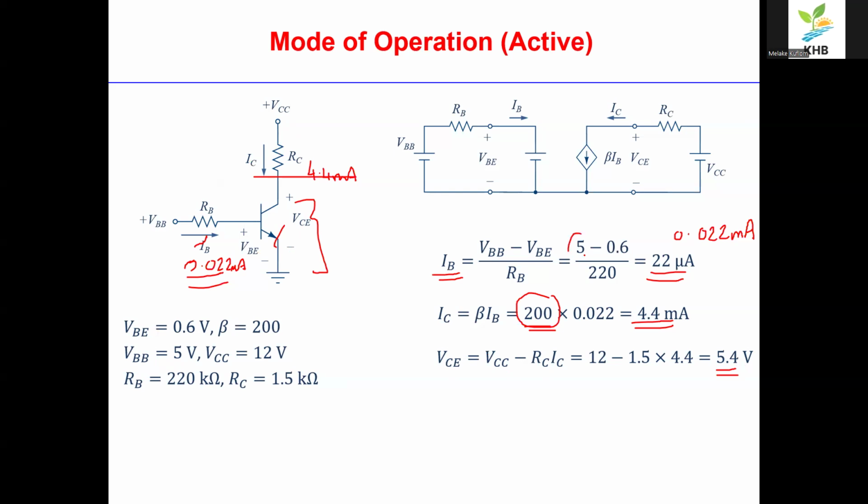Because if we have 5 volt input, VBE in here, 5 volt, okay? And then if the transistor is in a conductor or in a forward bias, VB is 0.6 volt. With a small amount of voltage, we can have a small amount of current. From that, we can have a large amount of current from here. So basically, we are controlling this by using this bias current, and then we can have a large amount of voltage in the VC region or in the output.